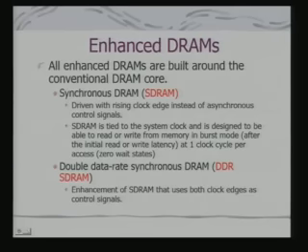So, you do not need what are called wait states. If RAS and CAS are asynchronous signals generated by the memory controller, the time taken to get the data would be more than the bus clock, the clock at which the system operates. So, the system would need to wait to get the data from the DRAM, and that is why wait states can get inserted. But if these RAMs can be synchronized with the bus clock or the system clock, then the wait state requirement can be eliminated, and that is the basic motivation of designing the synchronous DRAM.